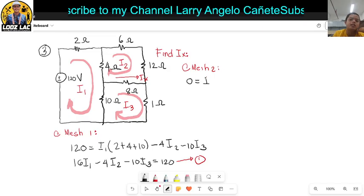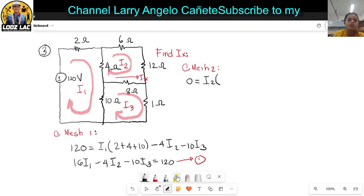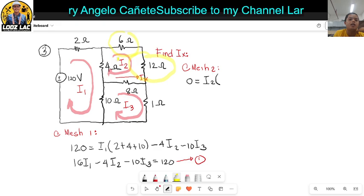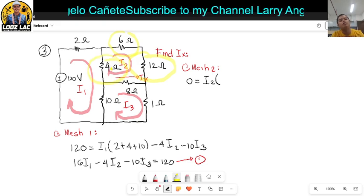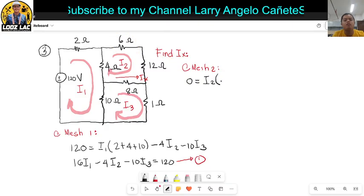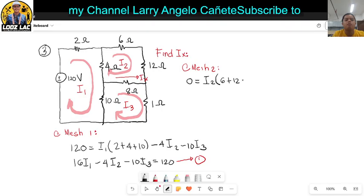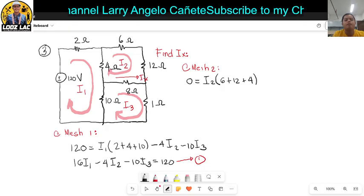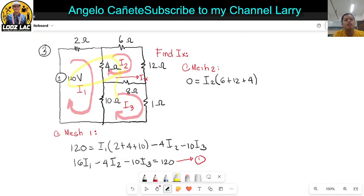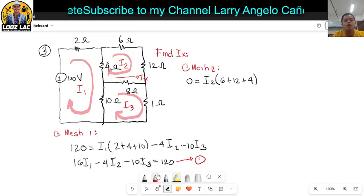You are inside mesh 2, so I2 here, times the sum of all resistors inside mesh 2: 6, 12, and 4. So 6 plus 12 plus 4. Then the 4 ohms and the 8 ohms are shared with the other side, so minus 4 I1